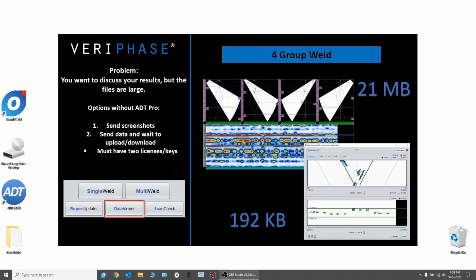When I started in the industry, phased array was not yet accepted by the codes, and there was a big enamor for radiography, because when you showed it to a client, it obviously looked like the weld. And I think we still lose some of that with phased array. On a lot of the instruments, you see the flip display, and people don't understand why their single V all of a sudden looks like a double V. And we start taking screenshots out and trying to explain to a client what's this big red blob and this and that. So just some things to keep in mind as we get into it.